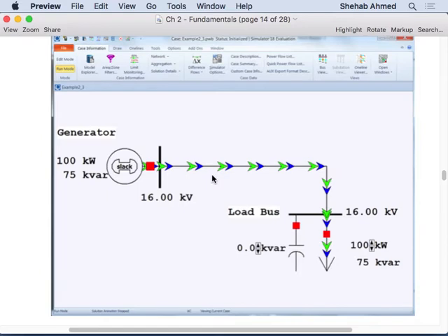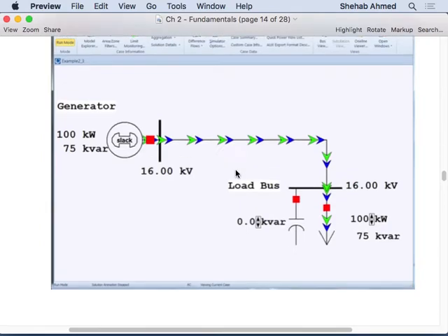Okay. So here in this case, we had a considerable amount of real and reactive power. We had 0 kilovars supplied by the capacitor. If you increase the kilovars provided by the capacitor, I think the blue is the reactive power, then you will find the size of one of these arrows going down. PowerWorld will let you do that.